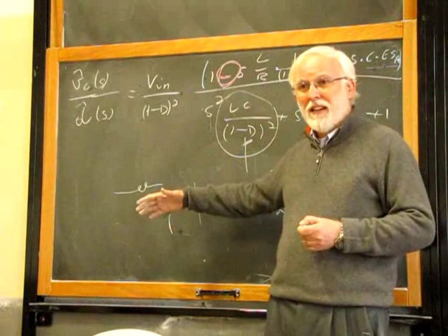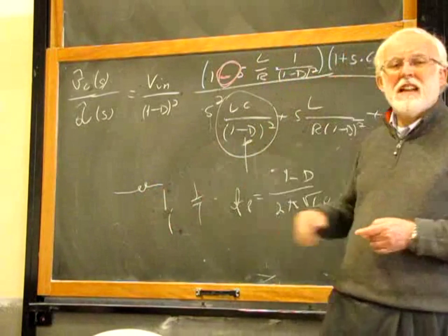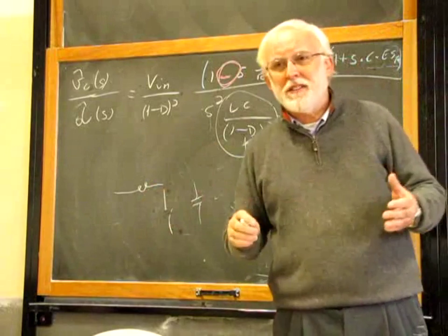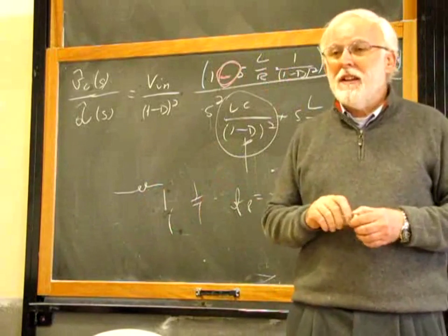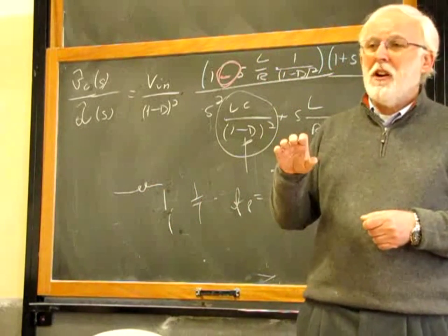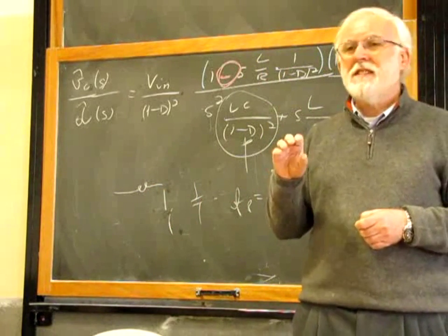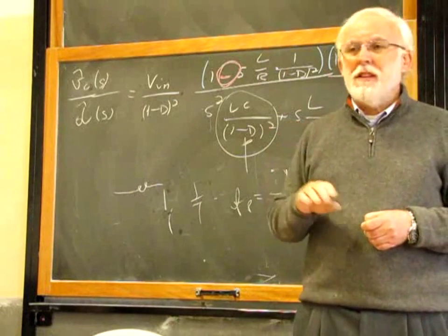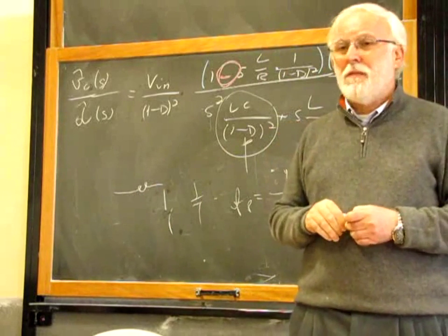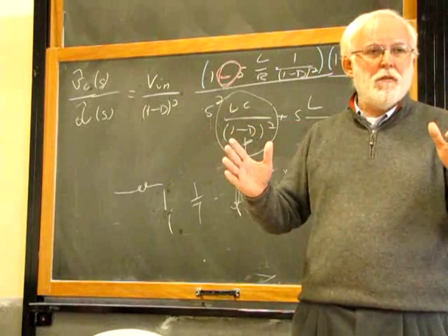That would be a smarter way. It's like, when you have an electronic circuit with transistors working linearly, instead of finding the bias point and substituting each transistor with its linear model, you write down the differential nonlinear equation for all your circuit and you try to solve it.